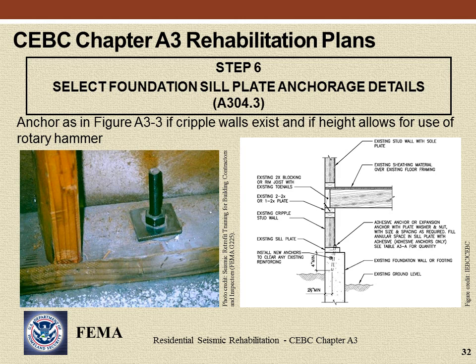Steel plate washers are required at each anchor bolt in the foundation sill plate. Sill bolts and bolting plates should always be galvanized because of the damp, under-dwelling environment. Steel plate washers, 3 inch by 3 inch by 0.229 inches, are required on new anchor bolts. See figure footnotes. Addition of plate washers on existing bolts is recommended where possible, but not required.